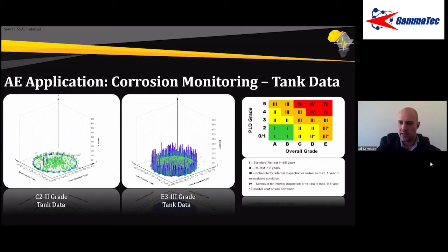Now, minimum detectable limit, I don't know if you're referring to that or the actual defect. Basically, if you have, for example, the SCC, where it's a very small crack or even micro cracking, we will detect it if our sensors are close enough and it hasn't attenuated out. So we could attach hundreds of sensors on an asset and monitor accordingly, but we need to then look at the cost to benefit ratio here. What is cost effective for the client to evaluate the asset? And in general, we can easily find very small cracks, 2, 3, 5 millimeters in an asset if it's growing in service.